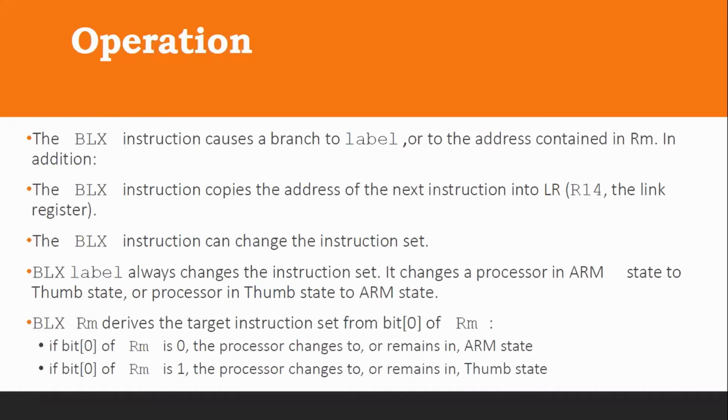The BLX instruction can change the instruction set. BLX label always changes the instruction set. It changes the processor in ARM state to Thumb state, or the processor in Thumb state to ARM state.